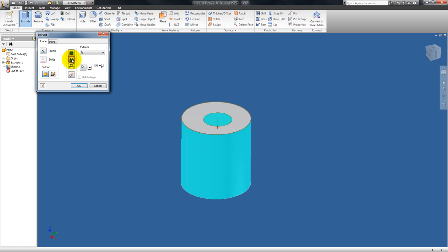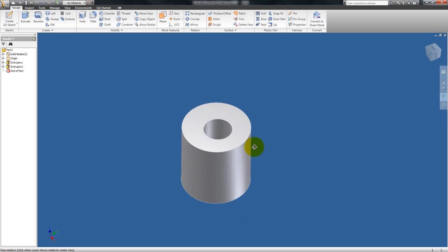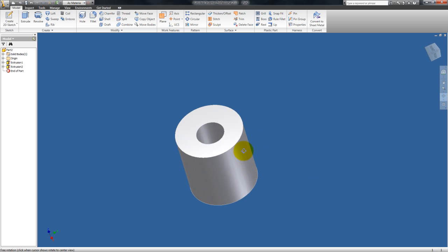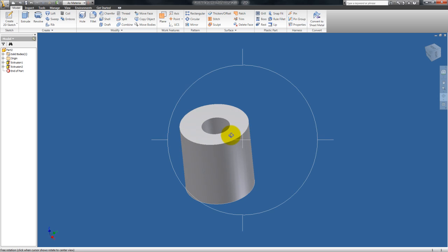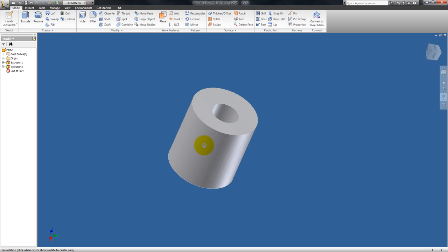We want to go cut. So if we enter a distance of cut, let's say 1/2 inch, it's going to cut halfway through. We've got a couple of options: intersect, cut, and join. So we'll use cut. So there we go. We've extruded a solid cylinder, and I've also showed you how to use the cut feature of Extrude. So next video we'll work on the Revolve Create feature.